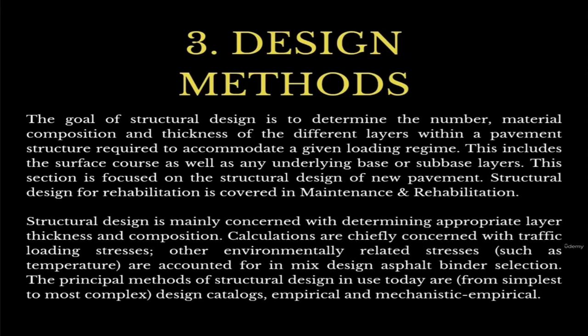So structural design is mainly concerned with determining the appropriate layer thickness and composition. Calculations are chiefly concerned with the traffic load stresses, and other environmental related stresses such as temperature are accounted for in the mix design for the asphalt binder selection. The principal methods of structural design in use today go from the simplest to the most complex: design catalogs, empirical, and mechanistic empirical, which is what we will touch on.